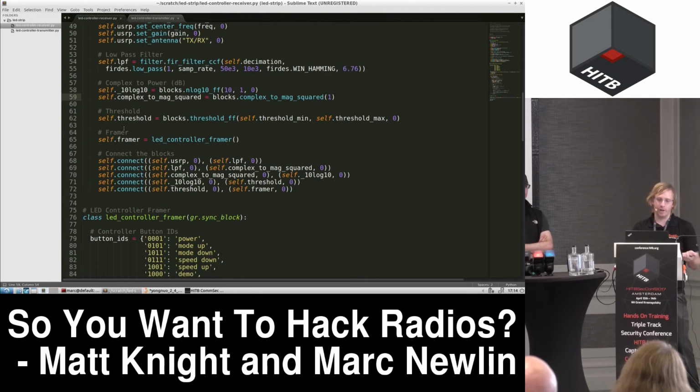We then have a threshold block. The threshold block will output 1s or 0s if the power is above or below a certain threshold. Right? And so the data is encoded, modulated, by turning the radio transmitter on, and then off, and then on, and then off. And so this will output 0s when it's off and 1s when it's on. We can then look in those 1s and 0s for the packets.